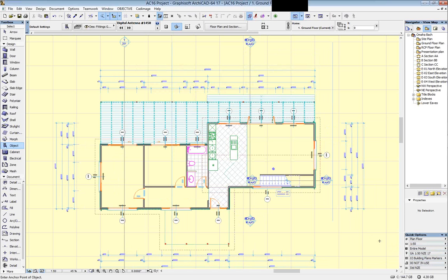Now, as I said, the big thing in ArchiCAD 17 is the introduction of the super attribute called building materials. Because they don't exist in 16, it makes them up in 17. What it does is it looks at all the composites and complex profiles you've used in ArchiCAD 16, and they've all been created using standard ArchiCAD 16 fills. So on the way through, it migrates those into building materials, so it just gets the name and all the properties of the fill that was in ArchiCAD 16 and pushes that as a building material in ArchiCAD 17.